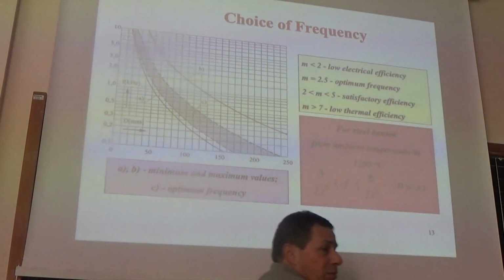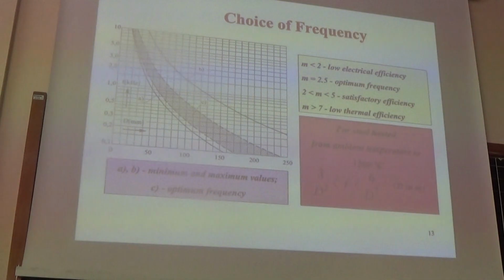This is from the theoretical point of view. But there is another issue, which is the possibility to produce inverters for different frequencies. It's much easier to produce inverters with frequencies above 2 kHz than below 2 kHz. And there is another issue, which is the noise.